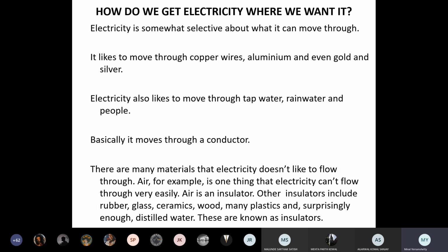If it is distilled water, electricity will not affect it. But if there are impurities, sulfur, phosphorus, these are good conductors, and you are in big problem if anything happens. And that's the reason why the meter room has to be protected. Last night we experienced the rain. Out here, the roads are flooded, my place is terrible. Now, if my meter room did not have the protection of a plinth and a high level, probably I would be out of electricity today.